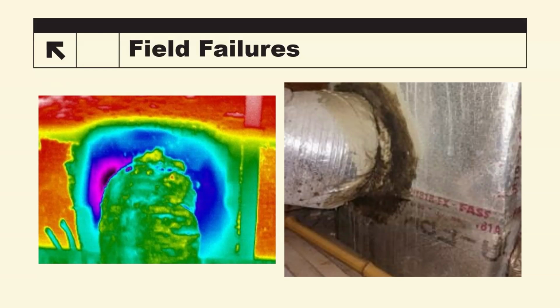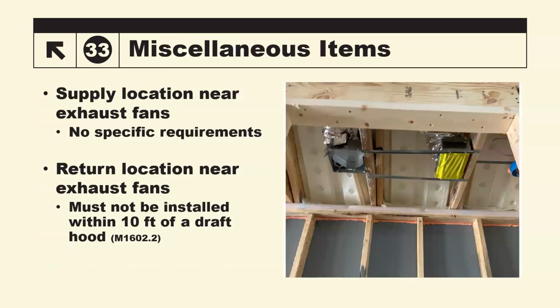So in my opinion, having insulated jackets masticked to the collar and/or plenum and not being able to lift them back and look inside to make sure that it's properly masticked on the collar before the liner gets put on, to me is key. I know there's a lot of HVAC contractors out there now that are masticking the insulation to the collar itself, and that may be something that somebody's requiring. But if you're not doing the inner lining correct to begin with, you're going to have a major problem.